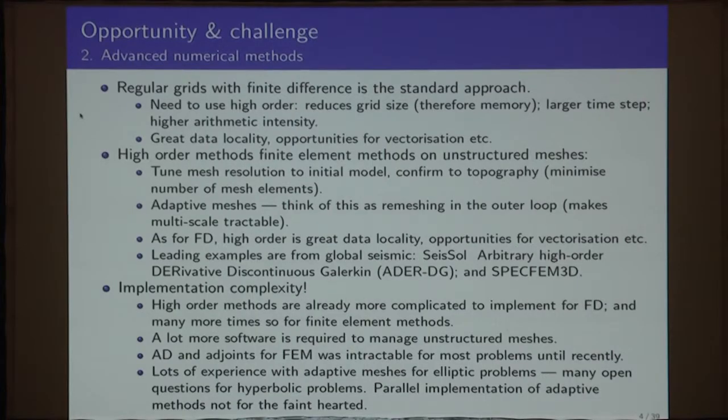But it's not your only error metric. There's actually a whole family of error metrics that people apply, and it depends very much on the nature of the problem. So it depends on you understanding where you're really incurring errors in the problem, and then using that to decide what your error should look like. Maybe I should have added some extra slides for that. But one thing that's always very good to keep in mind when talking about adaptive methods is that there are effectively two inputs. You have the input mesh, but the other thing that's much more important is a field that describes in some way what kind of mesh you ideally require to minimize or control errors in some mathematically rigorous way.